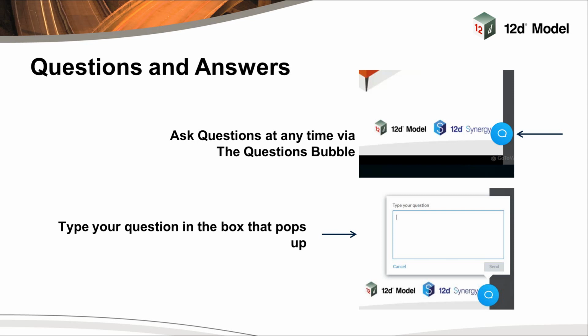Sure. And one from Rodney, can a grid be added to the plan using the MPS? Not within the preview. Again, it's a thing of the live data. So we've got 3 or 4 really neat little options in 12D that automatically can add a wheeled grid into a model that you specify. I think it's under CAD drafting in version 14.